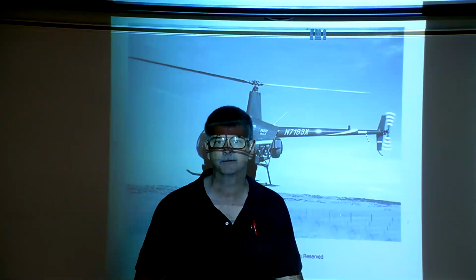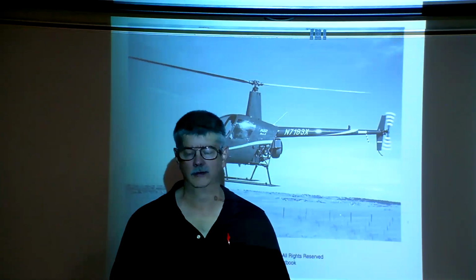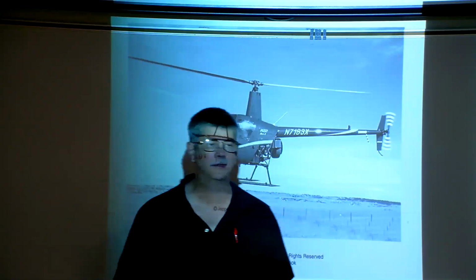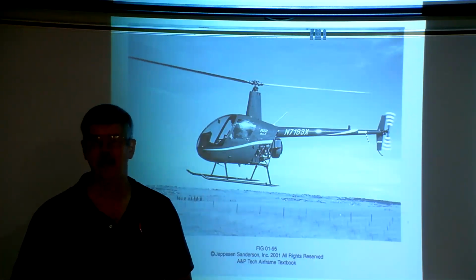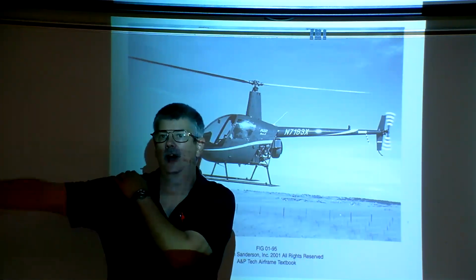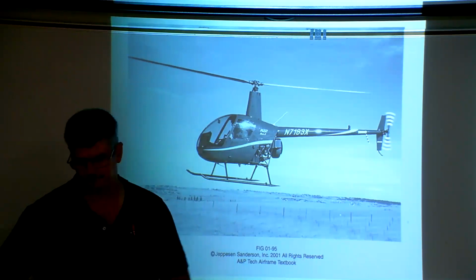Today, we have gone back to, and some helicopters are referred to as, rigid rotor, but what they have come up with is what's known as an elastomer bearing. All that means is a big rubber block, and the rubber block allows the blades to flap and to lead and lag.